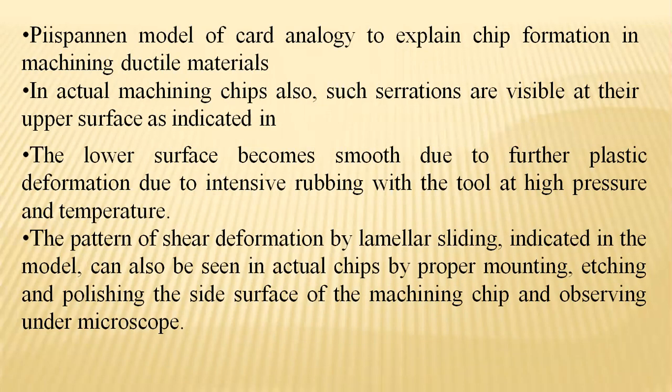In the machining of these chips, serrations will be visible at the surface levels, due to the following implications: the lower surface becomes smooth due to plastic deformation, upon the intensive rubbing by the tool over the work part at high pressure and temperature.